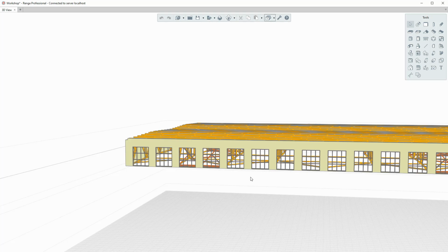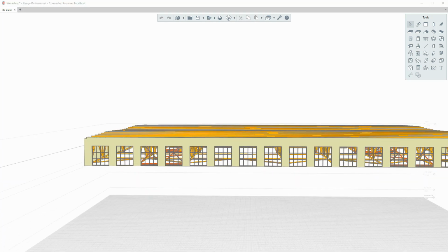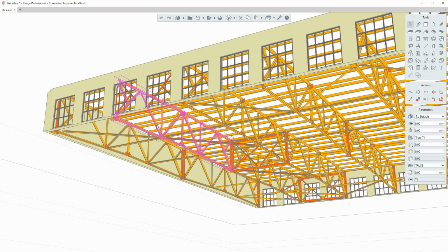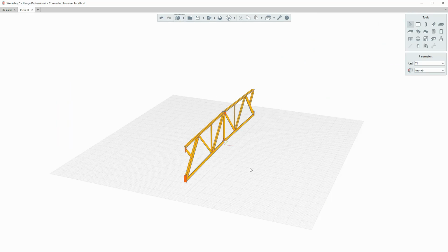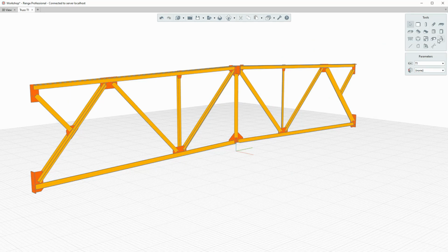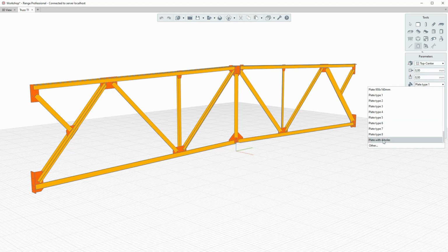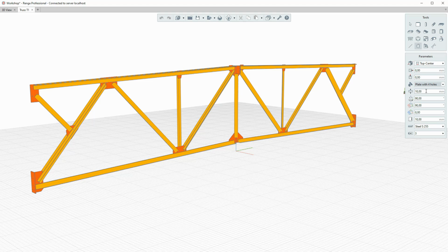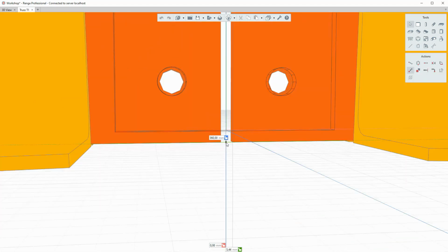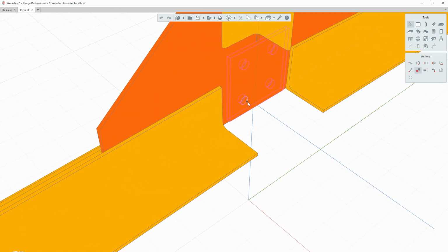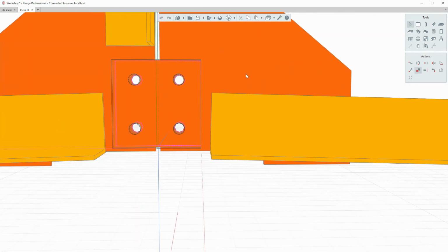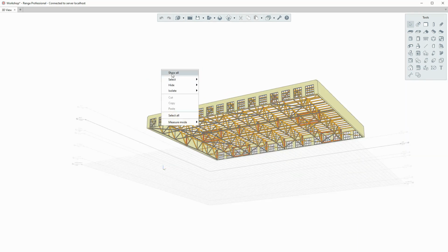To finish up, let's complete the building structure and add the created plate to the truss assembly. For that, on the Tools panel, click the Plate tool. Specify the plate parameters. And specify the insertion point. All the snaps and accurate construction are available for plate construction. Profiles are assigned to beams and columns in a similar way. This is the end of the 6th lesson.